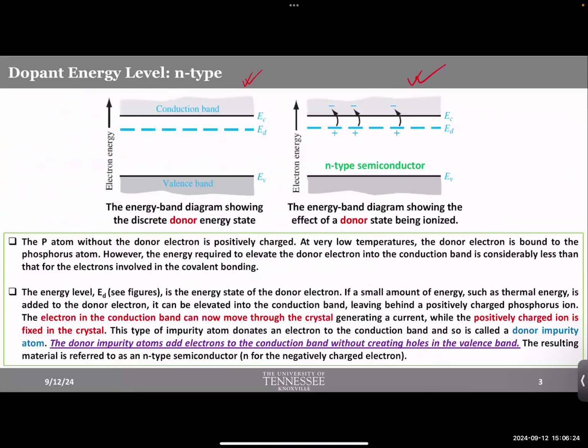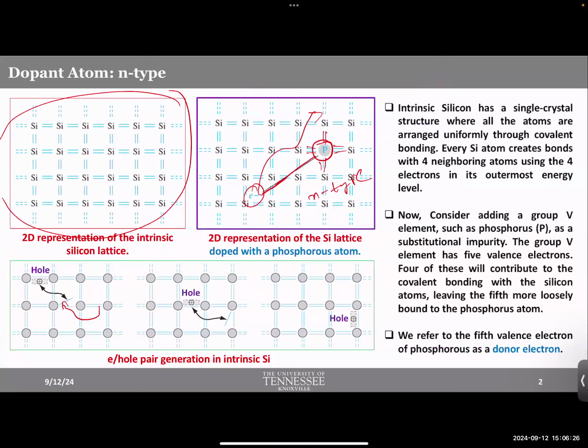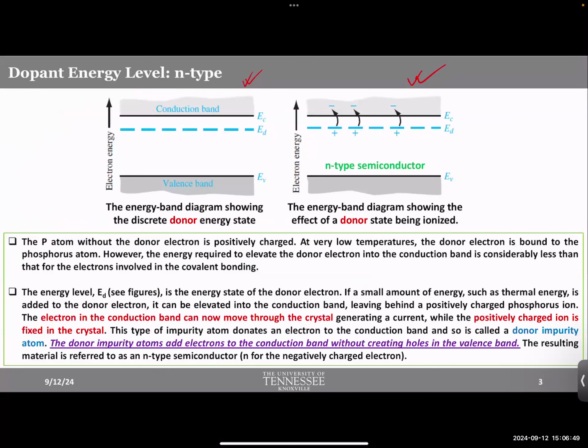Okay, now I'm going to use 2 names here. The type of material that creates an extra electron is called a donor, and the electron that you create is called a donor electron. Obviously, the other type of material, which has 1 less electron, is called an acceptor. So you have donor type impurity or acceptor type impurity in semiconductors. Just get used to these terms. Now let's see how the band diagram looks for donor type impurity and acceptor type impurity.